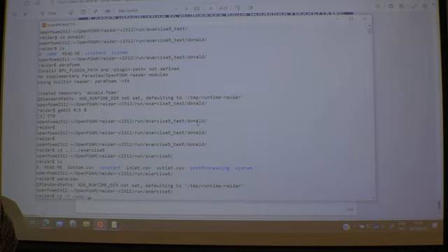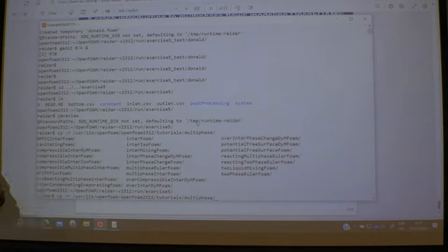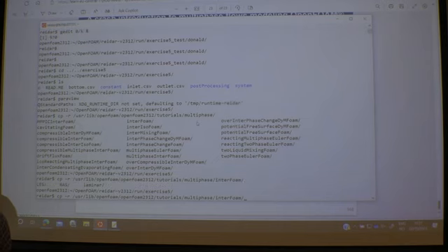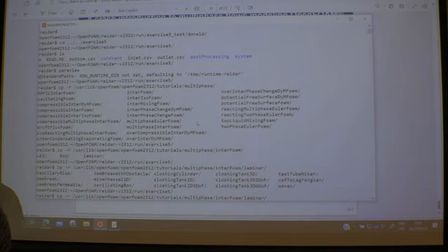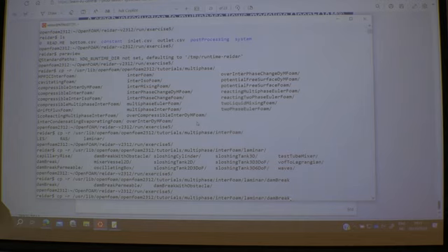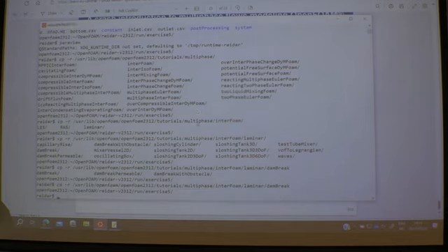Let's see, where do I have my OpenFOAM here? Somewhere, OpenFOAM tutorials. And here I have something multiphase. And under multiphase, you see you have a whole bunch of different OpenFOAM programs. So it's a huge area here. But let's start easy. The interFoam. And under interFoam we have a nice laminar little case. It's called damBreak. So let's take that one. So we just take damBreak and I copy it, and let's go into that one.